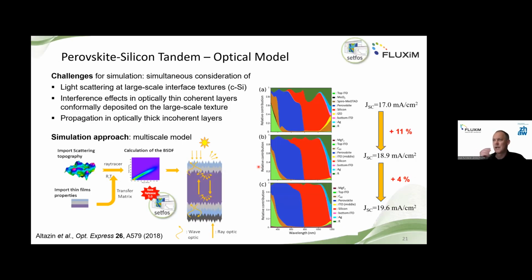But now I'm switching back to optical tandem calculation, especially for these high efficiency tandems approaching 30% PCE. They have to exploit light scattering. And this is also done with our software here, where we introduce textures for light scattering, which allows us to go from a more oscillating EQE giving low photocurrent to a more flat EQE spectrum with a higher photocurrent.